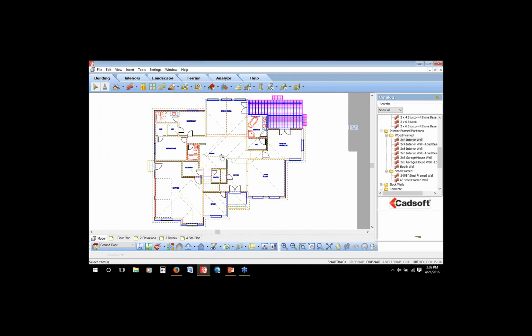You'll notice instantly then, after I've typed in the name and clicked OK, my cursor changes. Notice that it looks like a hand with a plus sign. And down in the lower left-hand corner of my screen, notice how it says Select Items. We don't want to bring the whole model out to 2020. They don't need all of the walls and the roof and the ceilings and everything. We want to reduce what we bring over so it's a smaller file size for them.